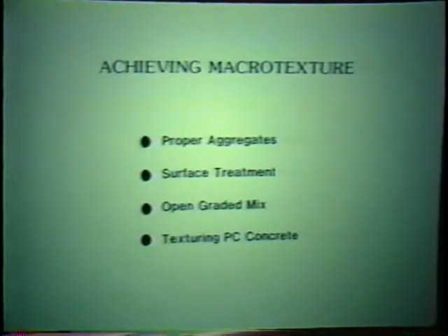Dense graded mixes can be improved with open graded surface courses or surface treatments or quality aggregate. Concrete pavements can be textured during construction. Macro texture can be provided on old concrete pavements by grooving.